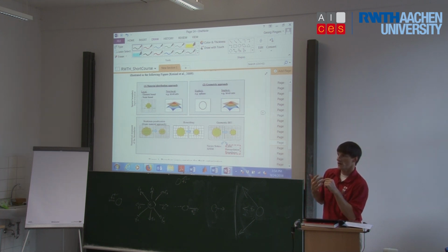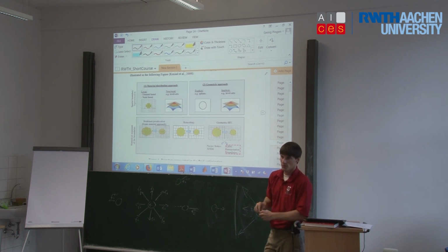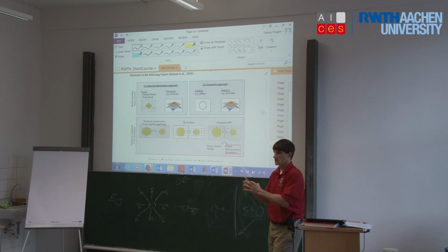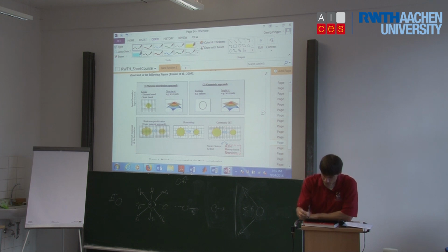And the reason for that is that oftentimes interesting physical phenomena are governed by boundary phenomena. So if what happens at the boundary is really important, so let's say you're looking at turbulence and you have boundary effects due to turbulence, if you represent the boundary with some porous sponge, you're going to lose everything you've been interested in. And so you can't really use that porosity-based approach. If you're looking at very well-behaved laminar flows at low Reynolds number, low velocity, then the error you get due to this porosity on the boundary is minimal, because the boundary is not going to be the driving factor behind your result.